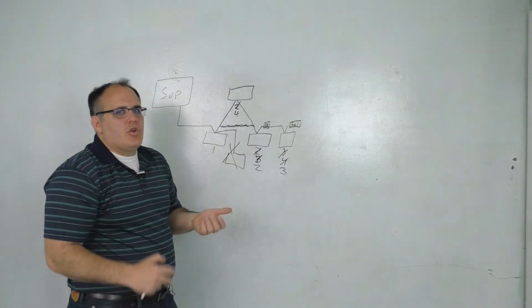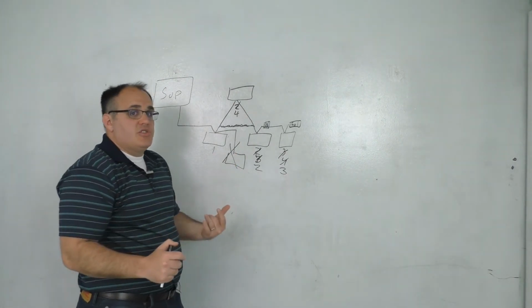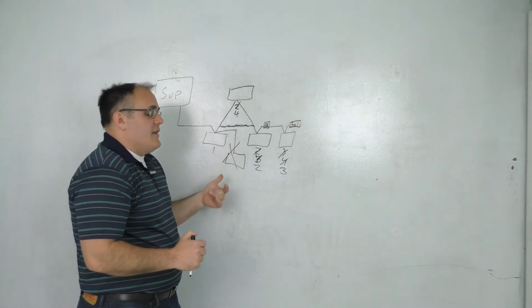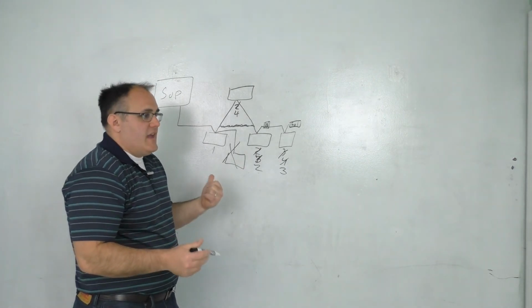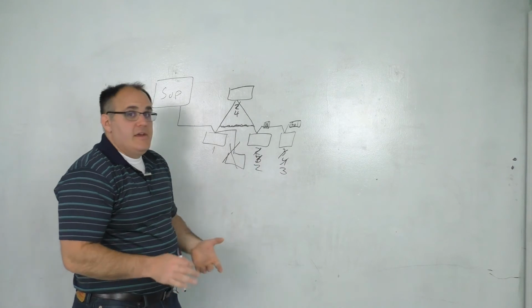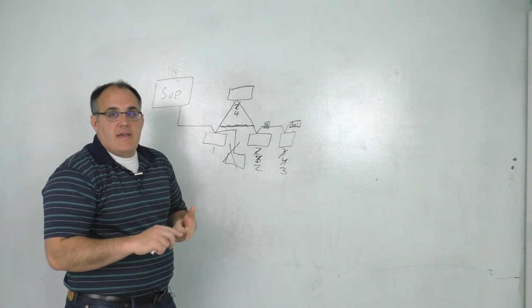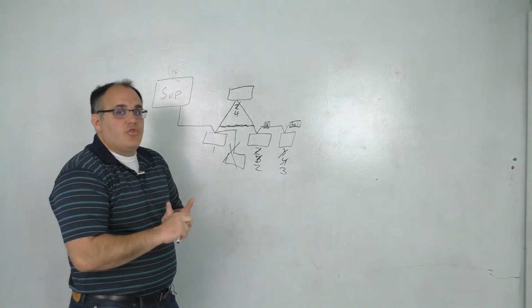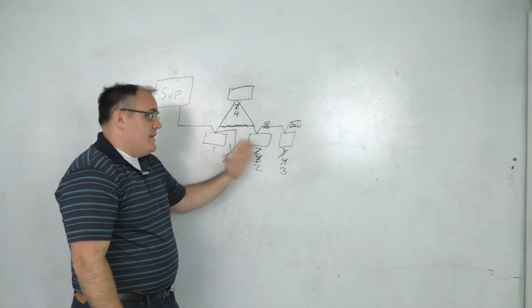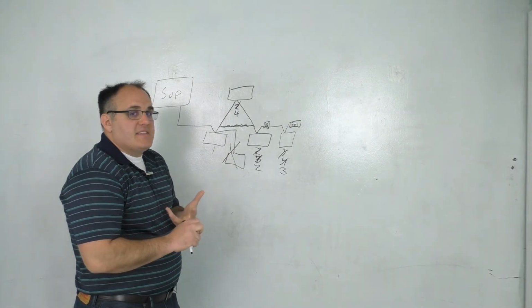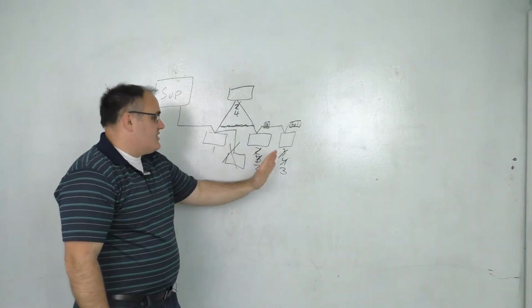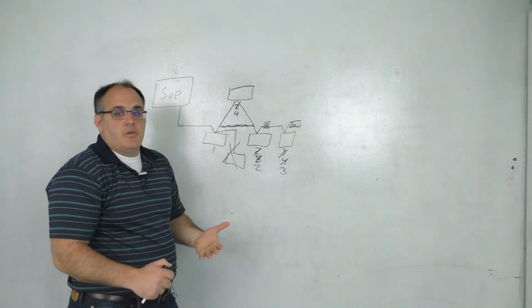If it's 1 or 2 controllers, it's perfectly fine. If it's 40 controllers, that's bad. You should just readdress, because readdressing and having sequential does what 2 things for us? If you're thinking, hey, it increases the speed of our trunk and it makes it easier for us to troubleshoot because everything's sequential, then you'd be absolutely right.